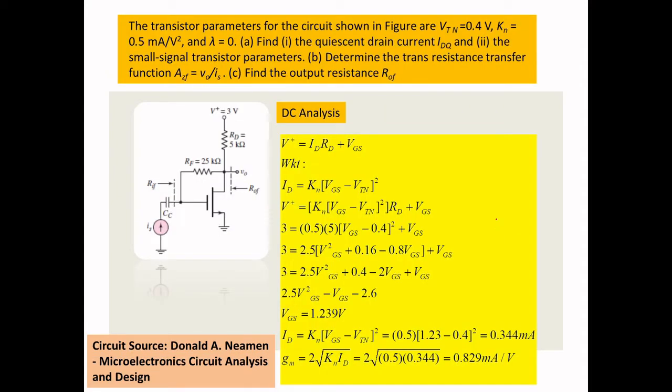See, in the circuit, I will explain why it is said to be shunt-shunt. This is your output. This is a common source circuit: source, gate, drain. I am taking the output at the drain. Your feedback is connected from the drain, so both are at the same terminal. So it should be a shunt. So shunt, I can write it as a voltage.